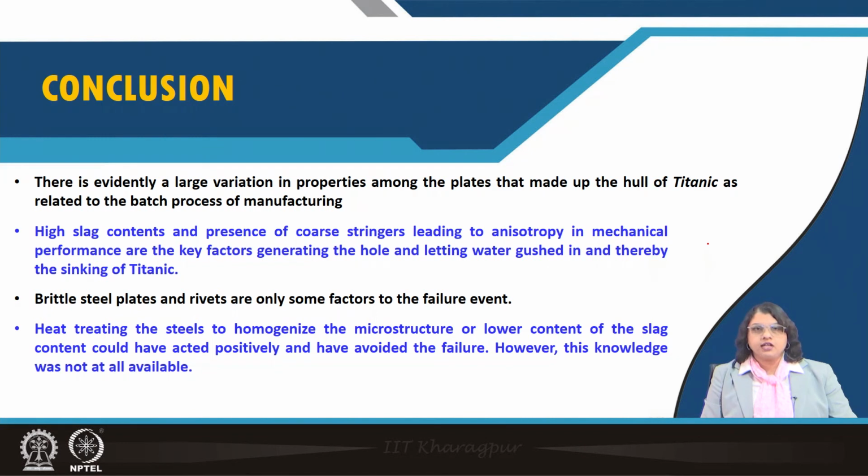In fact, heat treating the steels to homogenize the microstructure, that kind of concept was not available at that point, but if that had been done, or a lower content of the slag, it could have acted positively and avoided the failure. However, this knowledge, as I mentioned, was not available at that time, and later on people realized what important properties shipbuilding steel needs to have, and this has been maintained so far.